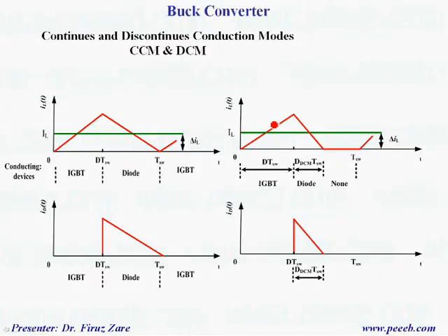In the previous section, we assumed that the current through the inductor is continuous. Now we are going to consider the discontinuous conduction mode. That means the current through the inductor is not continuous; before the next switching cycle, the current through the inductor reaches 0. In this case, we may have a different conversion ratio. This is a boundary case. If the inductor current is decreased, then we move to discontinuous conduction mode, or if the inductor current is increased, then we move to continuous conduction mode.